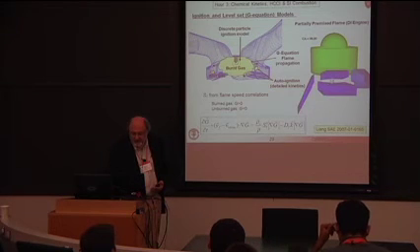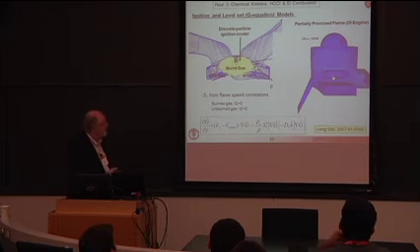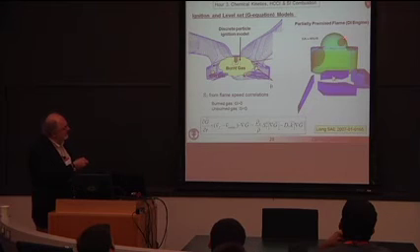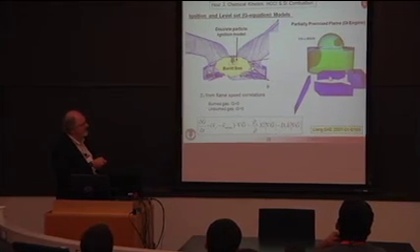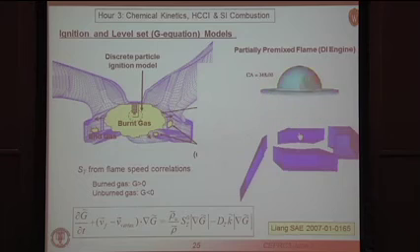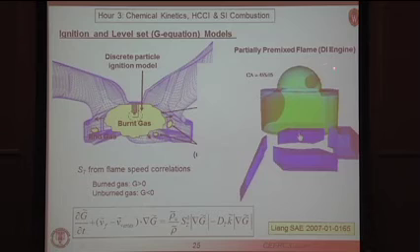So just to show a picture, this is a two-stroke engine that was modeled. In this case, we actually have direct injection of a spray and then the ignition. Now you see this circle that you see here. These are the ignition particles that I mentioned before. We just left them in the picture here. But basically, once the kernel reaches a certain size, we switch to the G model and then calculate the flame propagation. So look at that one more time. There's spray, ignition, and then combustion. You notice the combustion doesn't go all the way to the walls here because we have actually a lean quench occurring in parts of the chamber.